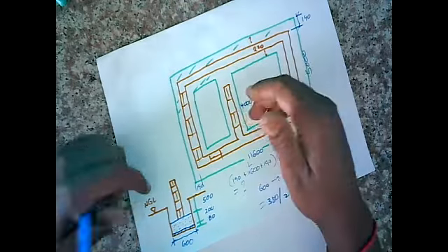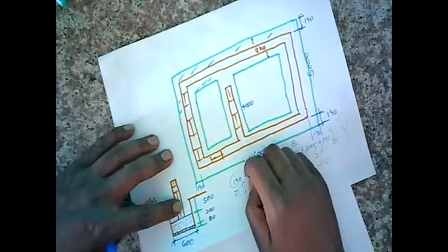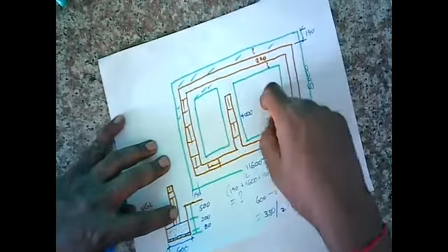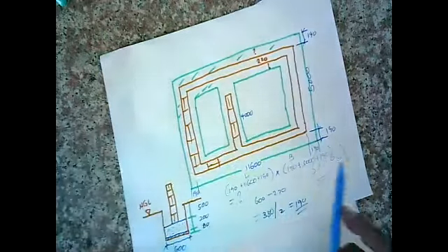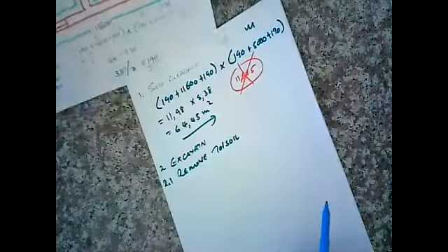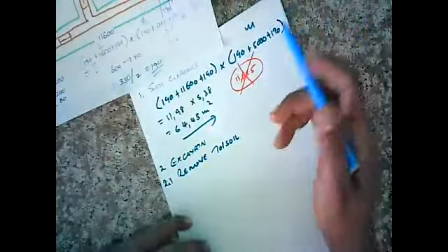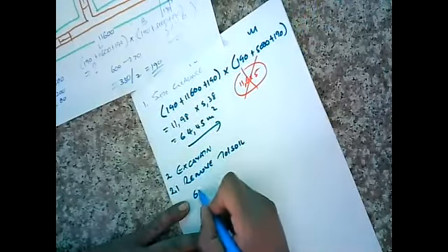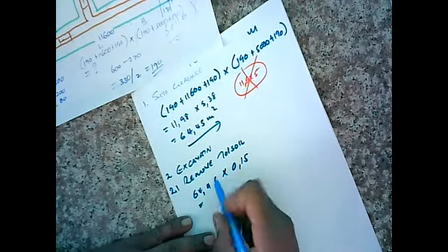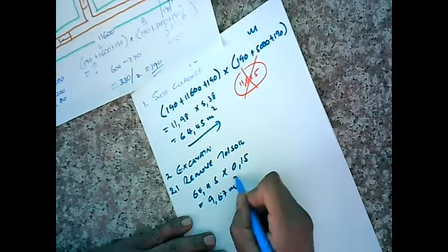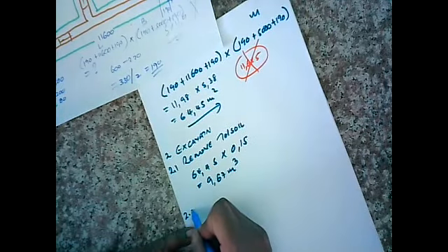Some students also say, you know what, we need to clear site only over there, and over there. So what if there's a big boulder there, and what if there's a huge tree there? We build around it? Think about the practicality of these questions. So we remove topsoil for everything, right? Because we create a space to work in. And we're saying 64.45 times 0.15, and you're getting a value of 9.67 meter cube. All right, what's next? 2.2.